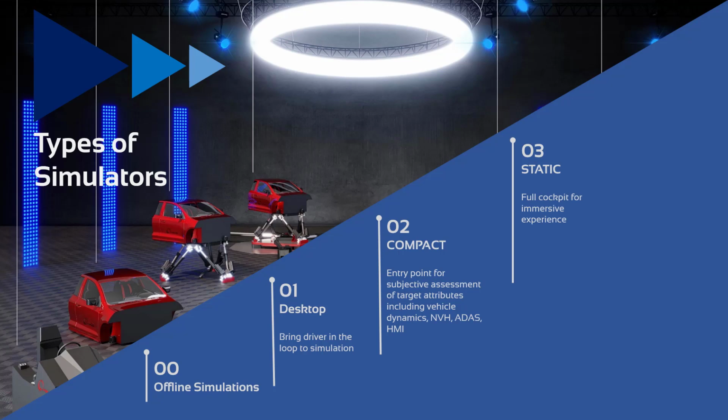The next level of simulator in terms of richness of response is a static simulator. This brings in the possibility of a full cockpit, even a full vehicle, for a richer visual environment that is particularly useful for ADAS and HMI scenarios that might even include non-expert drivers. And at the top of the spectrum is a family of dynamic simulators, the VI-grade Driver in Motion or DiM simulator family, that are designed to provide a large range of travel for longitudinal, lateral, and yaw dynamic response.